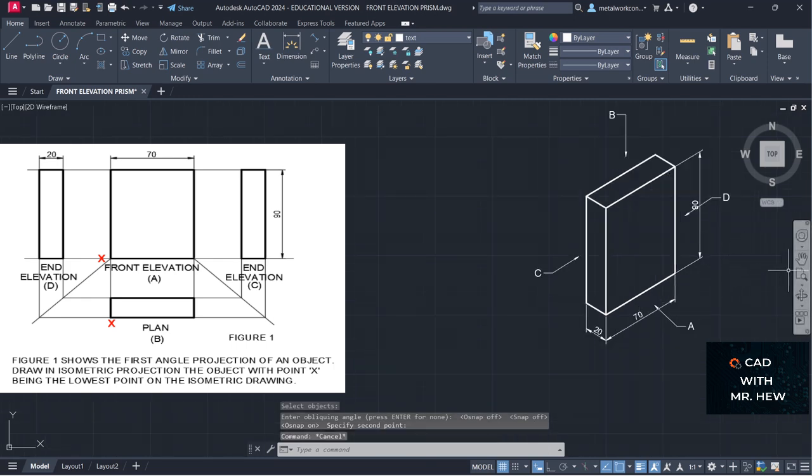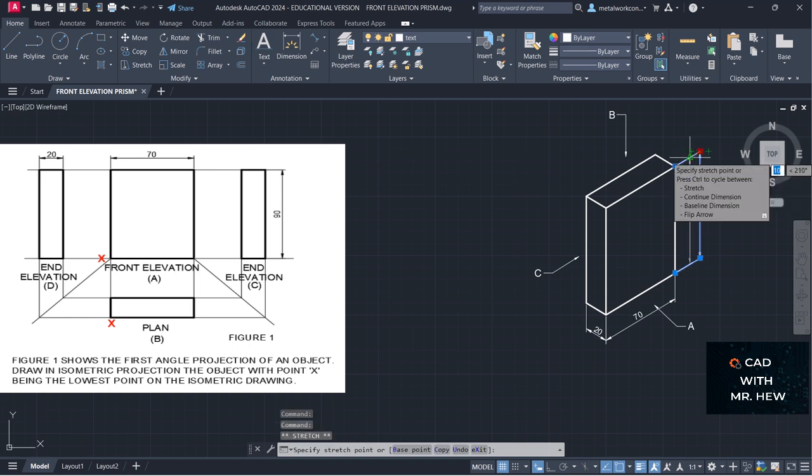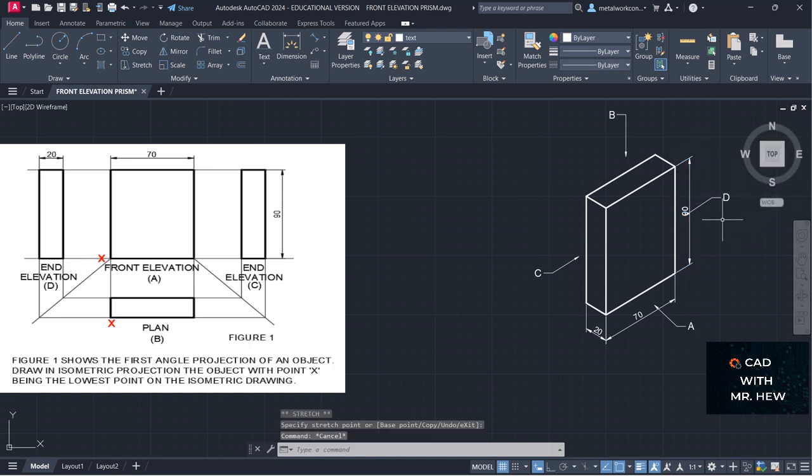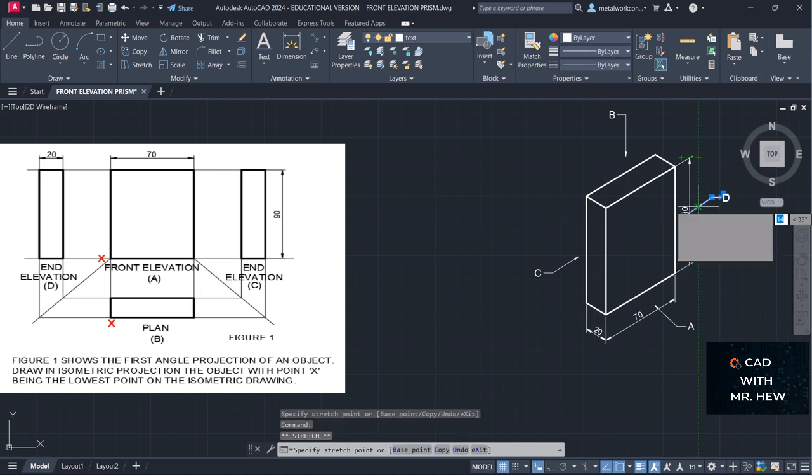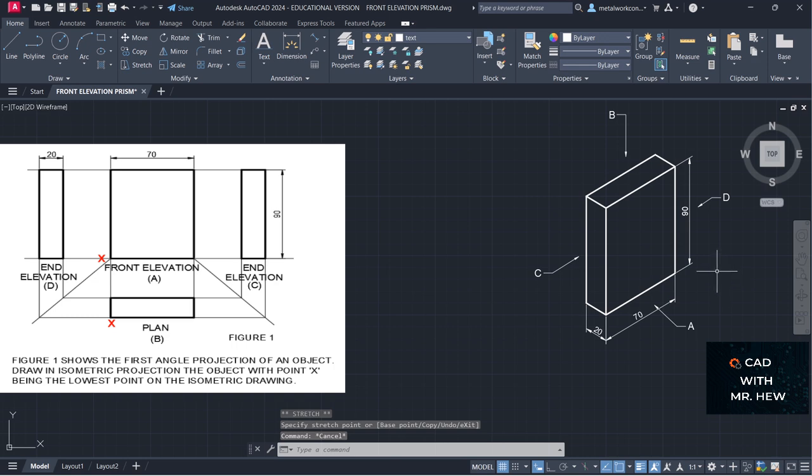Now the D, we're going to move the D so that it is not interfering, not in front of the dimension. So what we're going to do first, we're going to click on the dimension and we're going to move it closer. There. Then we're going to move this back. All right, so there it is. Good. We're going to do the same thing for here. We're going to move the arrow there. Good. So good job if you followed along.